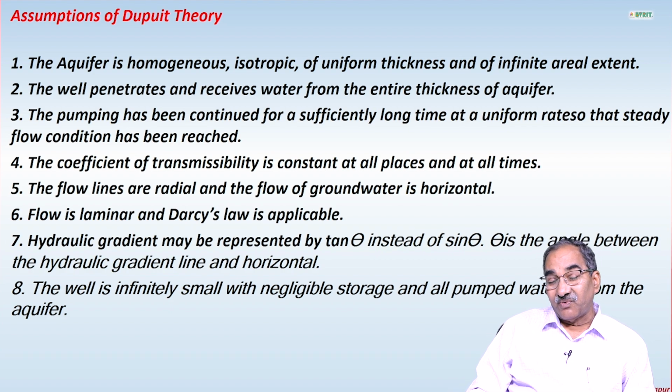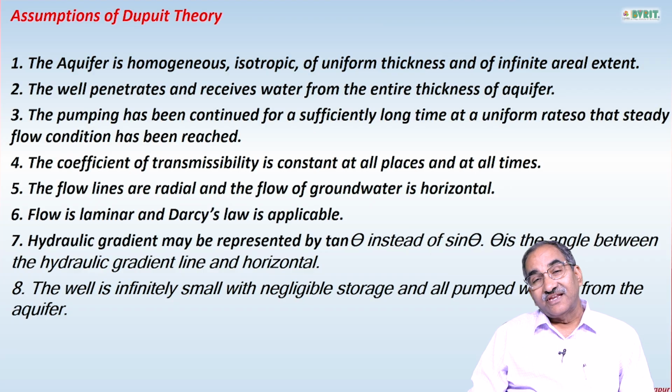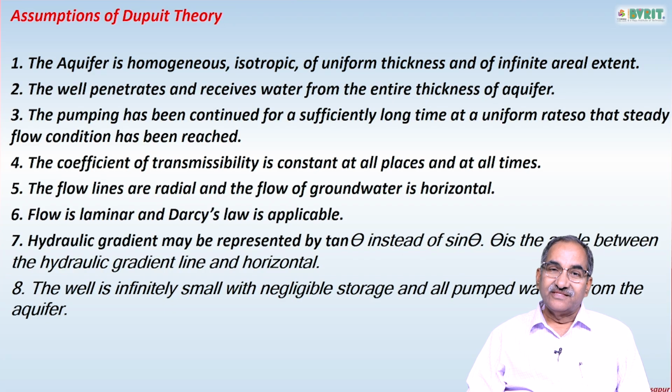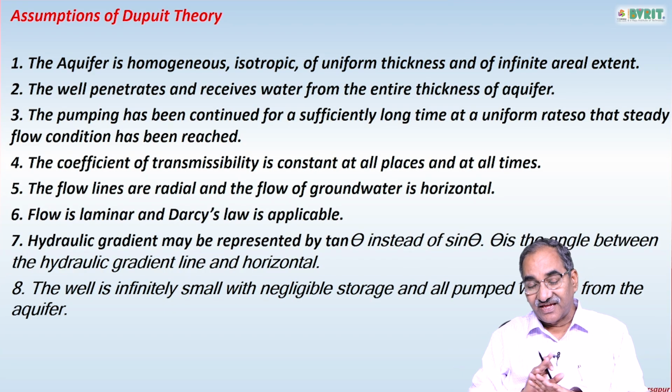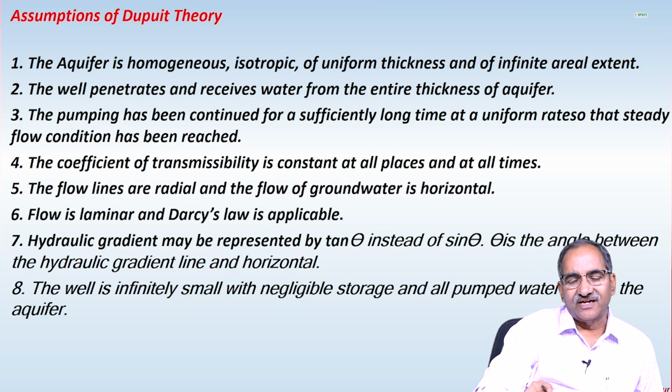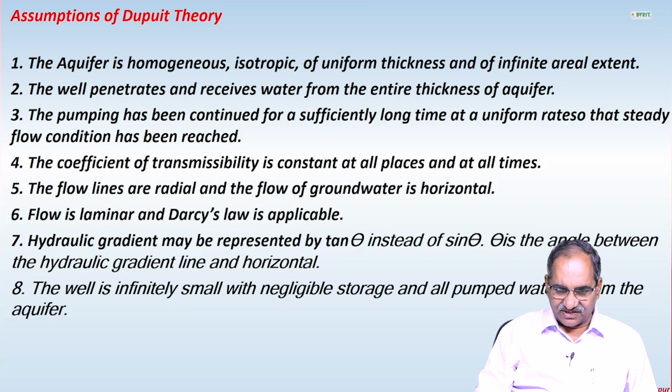Next, the last point is the well is infinitely small with negligible storage. So whatever water is being pumped, all of that is from the aquifer. The storage in the well is negligible. That is the last point. Very, very important, these Dupuit's theory assumptions.